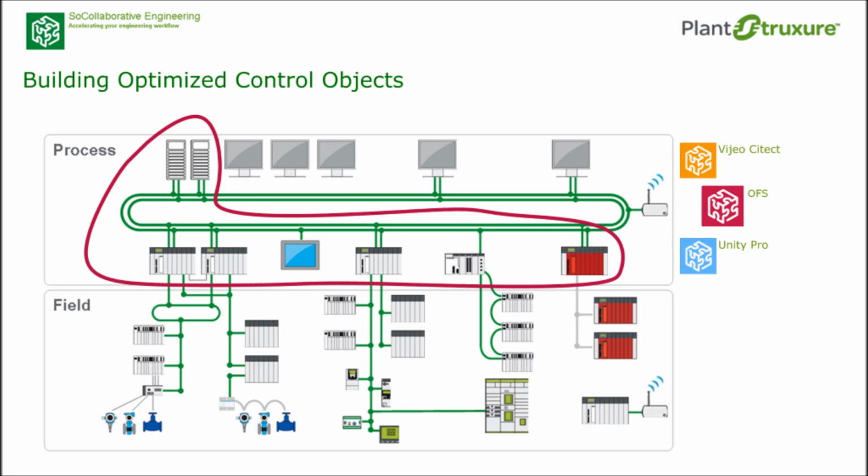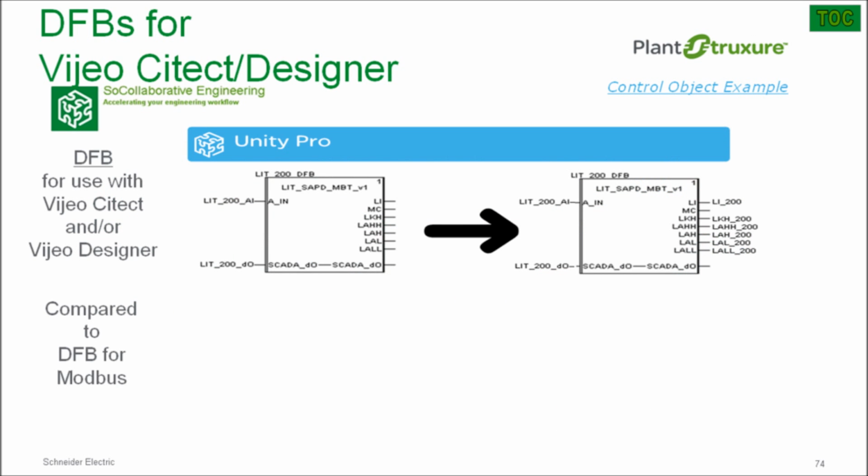Here is a basic comparison of the level transmitter DFB used for Modbus versus the one to be used with OFS OPC. Keep in mind that the code inside of these DFBs will be exactly the same to meet the requirements of the control specification.